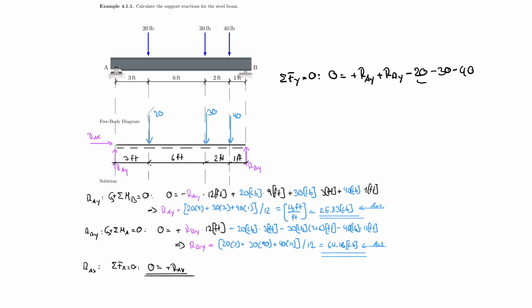And what you will find is that this here is equal to negative 90, and that these here are equal to plus 90, and therefore I can check it off. And I am certain that I didn't tell you anything wrong here. I actually found my correct results. Let's talk about this for a second again. So please understand that you always have to report 3 results for these support reaction problems, right? So you always have to provide RAY, RBY, and RX in this case.